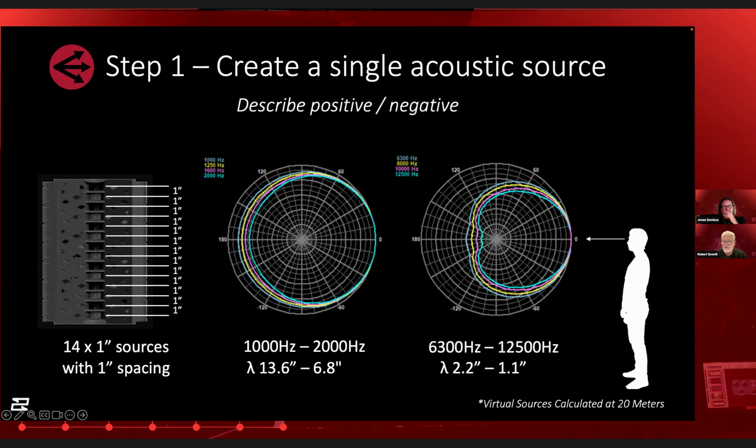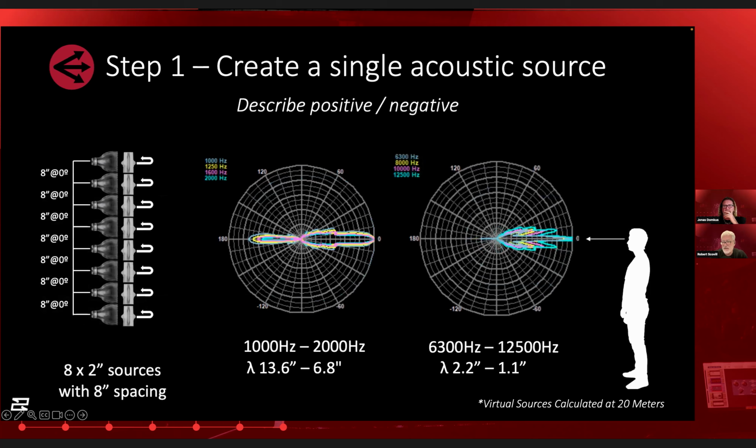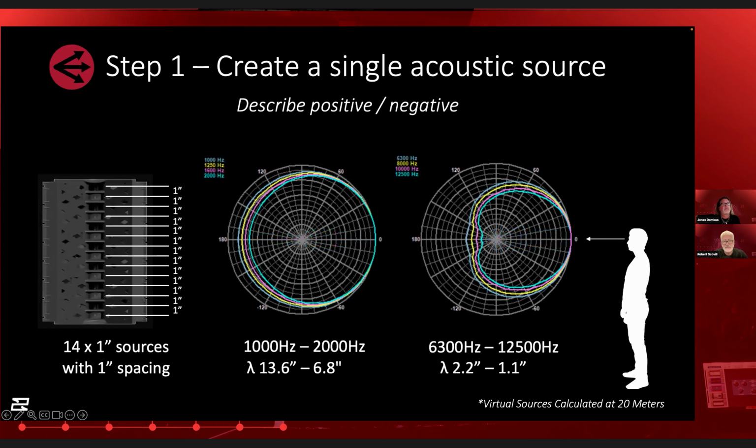We're essentially just releasing audio back to where it originally wanted to go, right? And by doing that, through use of delay, equalization, amplitude, all very, very basic DSP components, we can create a polar of nearly any shape in that vertical setting. If we go here, we can't really do that, right? Even if we put DSP on every component here, our ability to reshape the polar is not really there. We don't have the overlap between the horns in order to be able to do it to any effective scale, right? So, and we'll dive in on that going forward here.